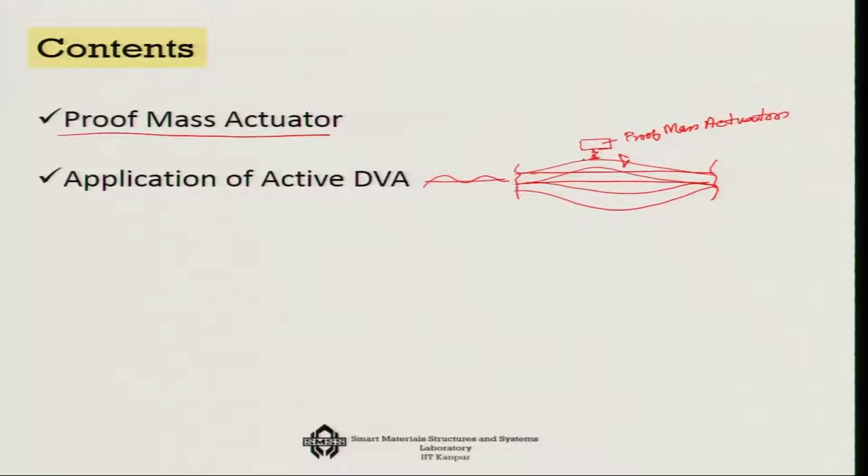So, when this is going up, at that time you apply a force which is going down, dynamically and back and forth like that, so that you can suppress the dynamic response of the system. That is why this is also sometimes known as a sky hook damper.